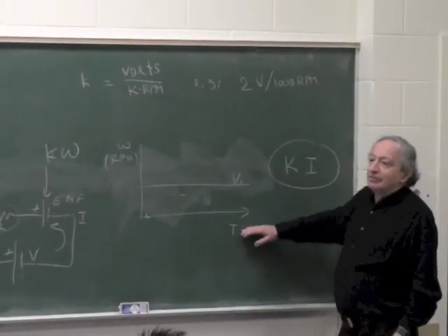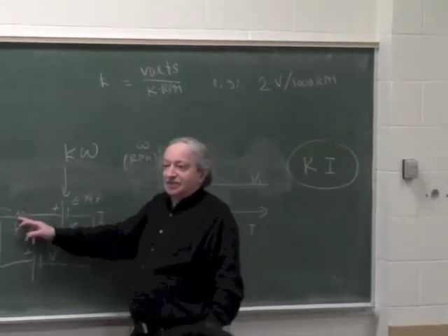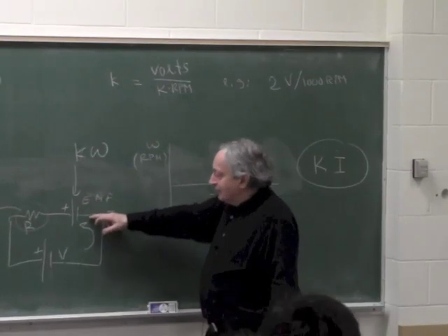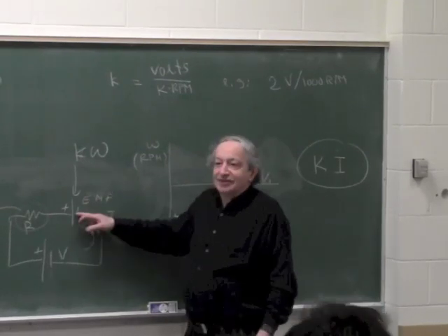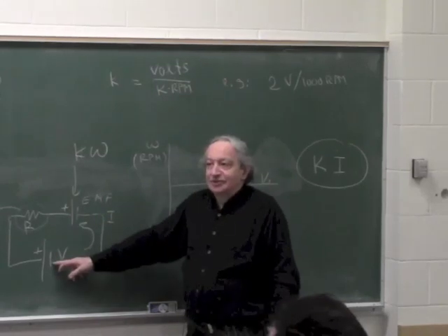Now the reason why it will be regardless of torque, because if there is really no resistance here, if I try to lower this EMF, the current will become infinite again. So regardless of torque, this voltage has to be equal to this voltage.